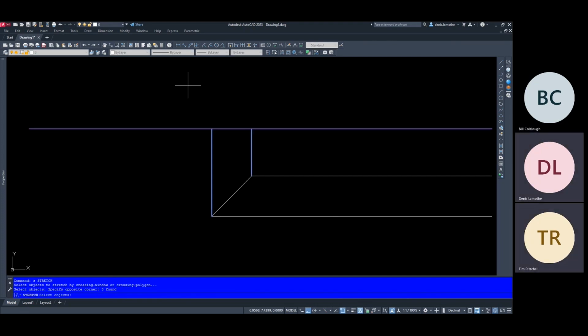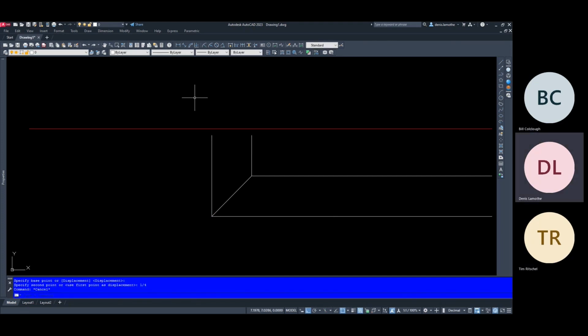Okay. And in addition to that, we will leave a bit of a gap between the wall and the handrail of about 1/4 inch. So that allows if the wall varies, the drywallers aren't always the best, most precise trade in the world. Framing could be off a little bit as well. So that wall may have a bit of a wave to it.